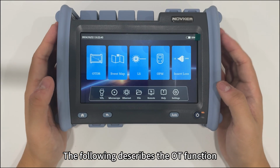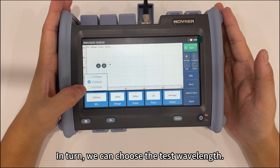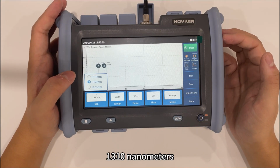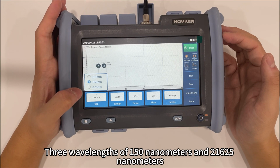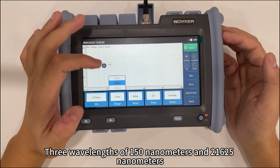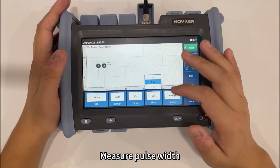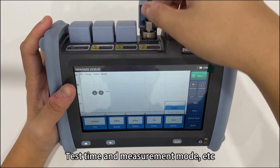The following describes the OTDR function. In turn, we can choose the test wavelengths. This device has 3 wavelengths, 1310 nanometers, 1550 nanometers, and 1625 nanometers. Test range, measure pulse width, test time and measurement mode, etc.